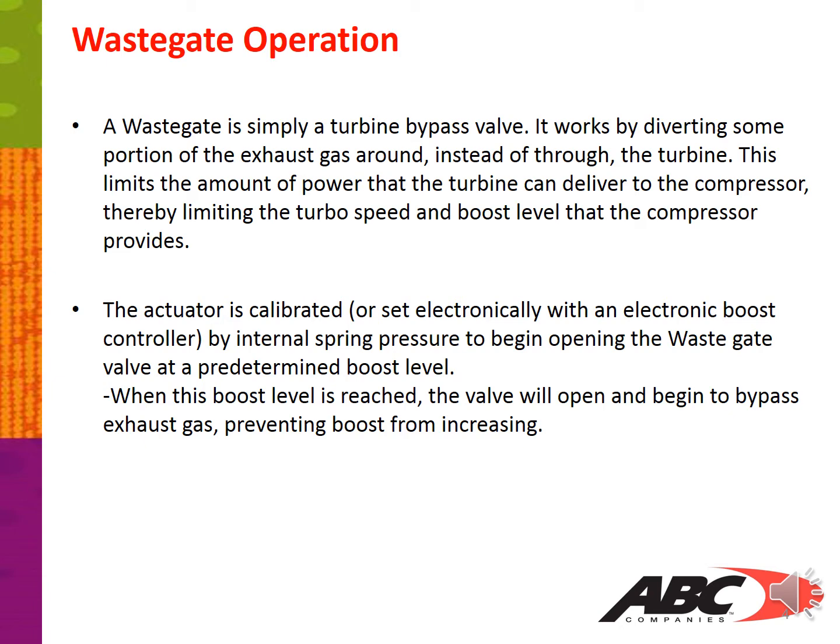The actuator is calibrated, or set electronically with the electronic boost controller, by internal spring pressure to begin operating the wastegate valve at the predetermined boost level. When the boost level is reached, the valve will open and begin to bypass exhaust gas, preventing boost from increasing.